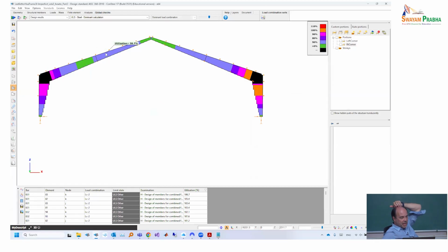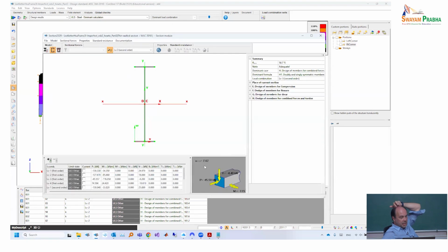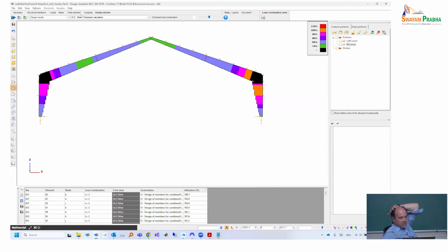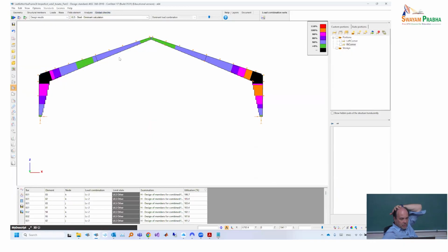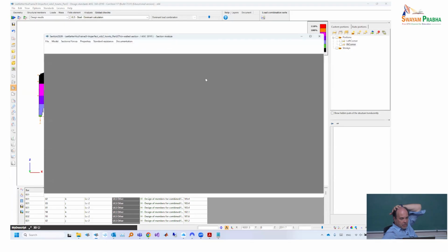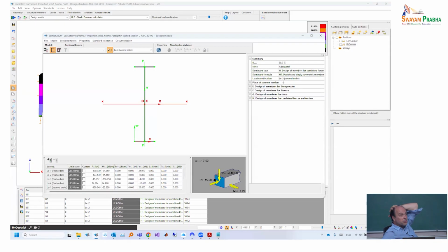And now, for example, if we select this less exposed cross-section here, we can see that a buckling mode with 7.62 was chosen. This is certainly not the first and not even the second. We haven't even seen which one that is. Yeah, that was load combination 3. So here, not even load combination 2 is relevant, but load combination 3.